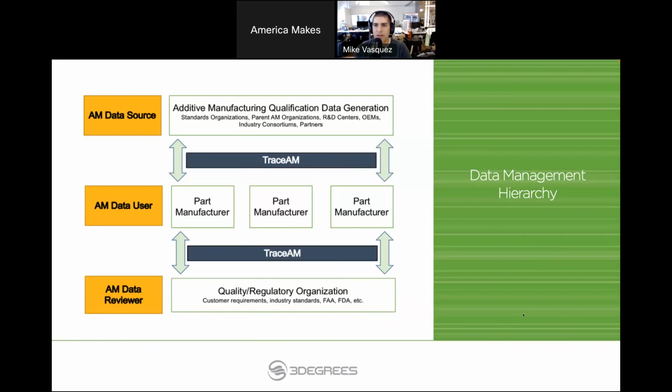And so oftentimes that comparison is quite difficult because you don't always have the right parameters that make comparing two data sets consistent. So if I'm doing some builds and all my layers are at 40 microns and I'm going to compare to a data set that's 30 microns or 50 microns, that may not be exact apples to apples. So at least knowing that is something that people want to know, certainly in the industry.